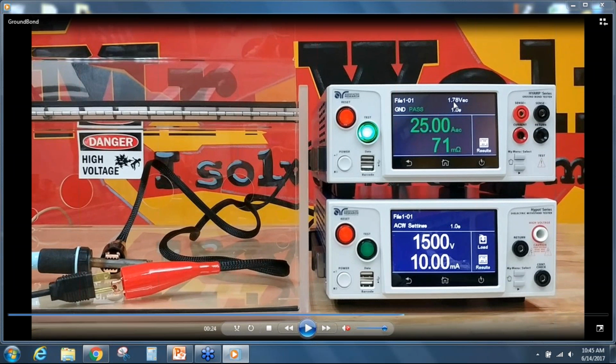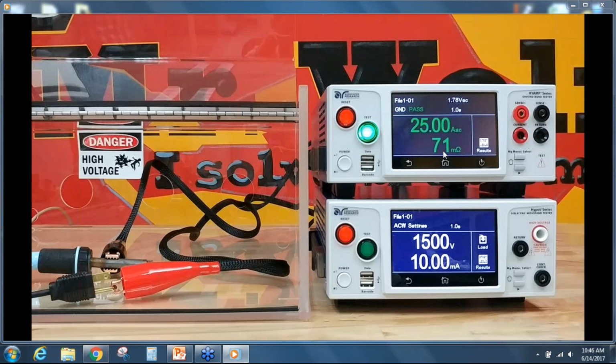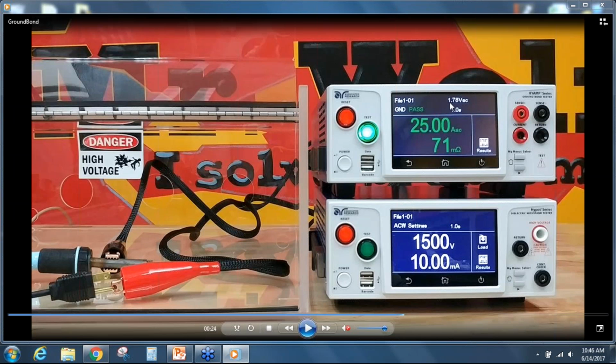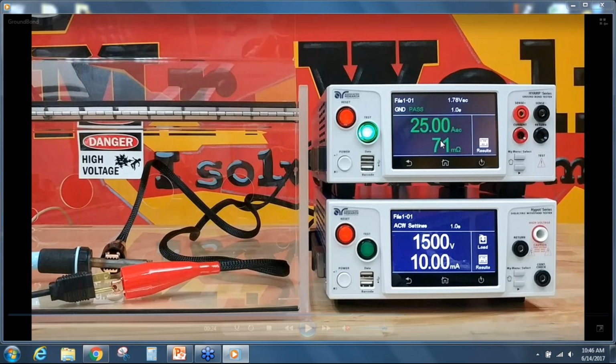Now, one thing to note here is that we start including with our new tester the voltage drop. So if your standard does not care for the milliohms reading and they actually call out for voltage drop, you could actually drag this meter down here, and now you have a measurement that's in voltage. So if the standards call out for do not drop more than 2 volts across your DUT, that indicates I'm still passing it because I'm not dropping more than 2 volts across it. I'm only dropping 1.78. Again, Ohm's law is in play here. So previously, most of the equipment or instruments did not display voltage drop, and for the standards that require this, it will have to be calculated outside of the instrument.